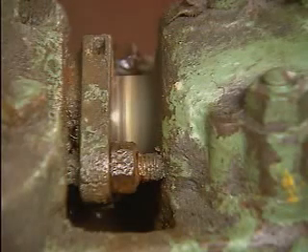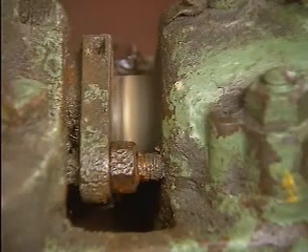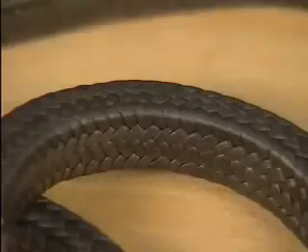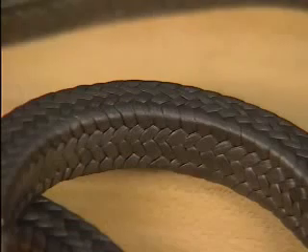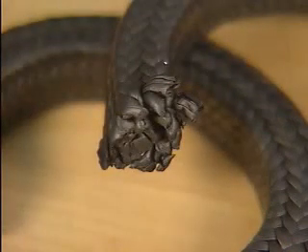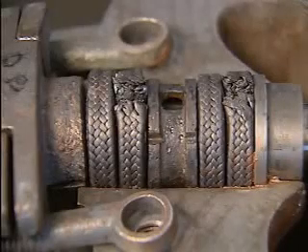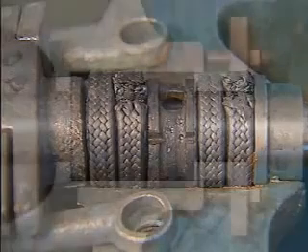One way to control leakage around movable parts of equipment, such as pump shafts and valve stems, is to use packing. Packing is generally made of tough fibers that are woven together or pre-formed with other substances into a rope-like material. Packing is typically contained in an assembly called a packing gland.